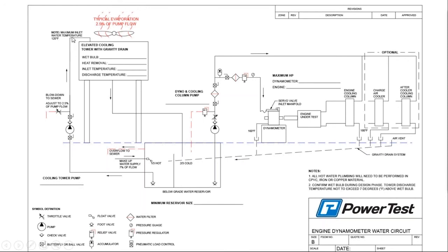So here we go, we're walking up through the system, and here we're indicating wet bulb temperature and heat removal. In this case, remember we said 2,100 over here, and the same for the engine. So what does that add up to? My mathematician cohort, I know you don't know this because you're too good at talking in that math. So this is 4,200 horsepower. Inlet temperature is the temperature going into the system. Typically that's recorded at 120 degrees F.